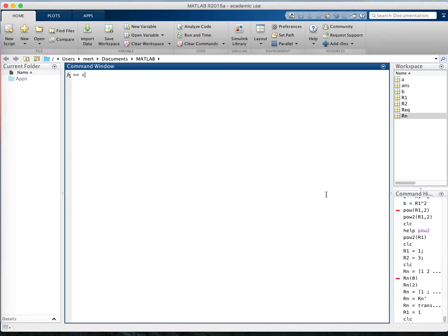But if I use clear, I lose everything. Clear clears everything in your workspace. This is important because I'm fast in writing and sometimes mix up clc and clear, and sometimes I clear my workspace. So be careful, you can lose everything. This is one of the reasons it's sometimes bad to work in the command window.